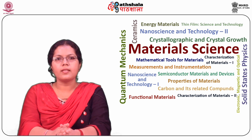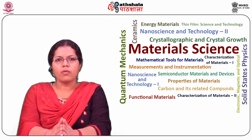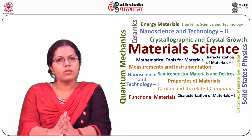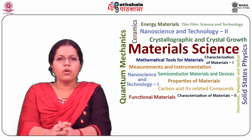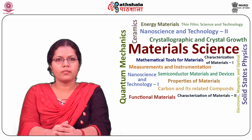Hence, the inductance of an inductor constructed with ferromagnetic cores depends upon the value of the current passing. In order for inductance to be independent of the current passing, air-cored coils should be used for standards of inductance.